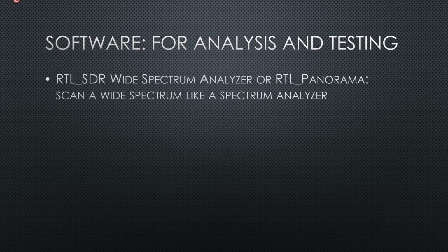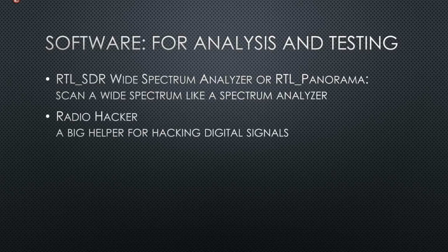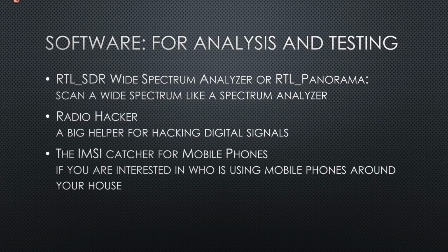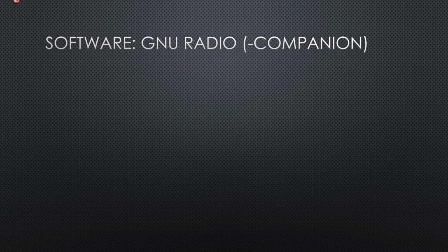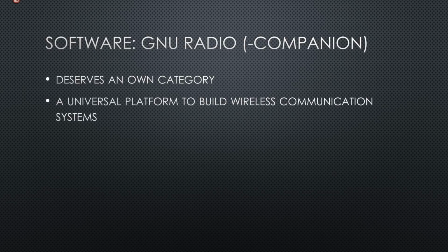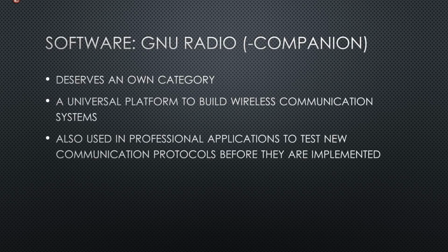For example, RTL-SDR Wide Spectrum Analyzer or RTL_Panorama. Both enable broad spectrum scanning like a spectrum analyzer. Or Universal Radio Hacker, which is a big helper for hacking digital signals. And of course, the IMSI catcher, if you are interested, which finds the mobile phones around your house. GNU Radio deserves its own category as a universal platform to build wireless communication systems. It is also used in professional applications to test new communication protocols before they are implemented in mass-produced devices.